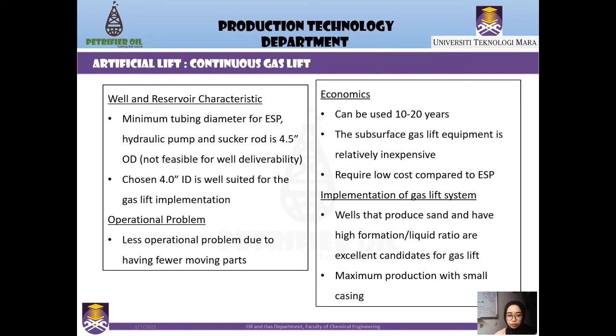From the point of view of operational problems, there are fewer operational problems due to having fewer moving parts. The next one is from the point of view of economics. It can be used up to 10 to 20 years. So since our life of production is about 10 years, it is economically viable to use gas lift over other artificial lift methods. The subsurface gas lift equipment is also relatively inexpensive, as well as